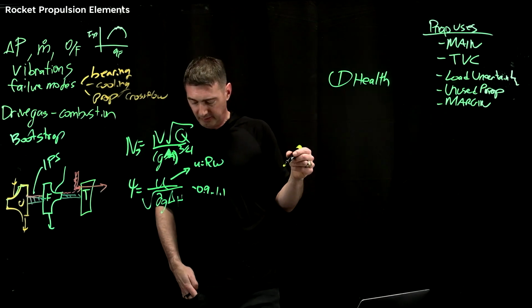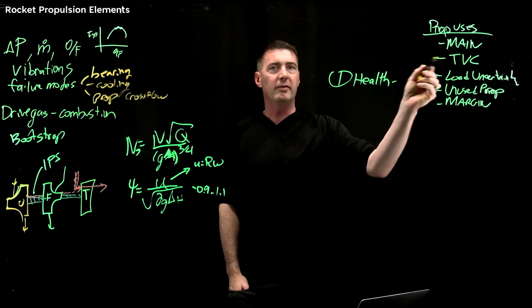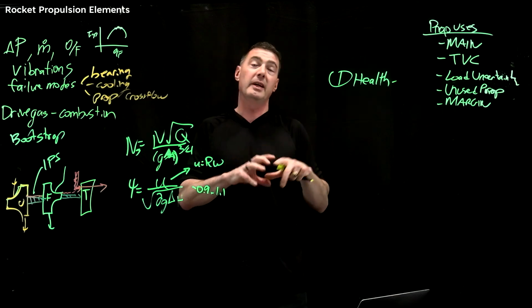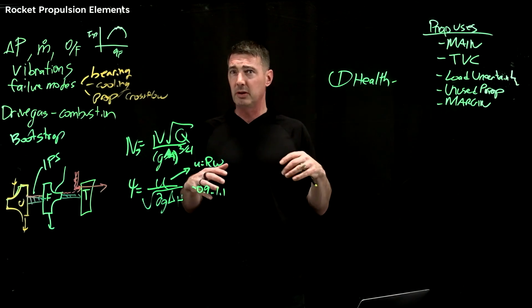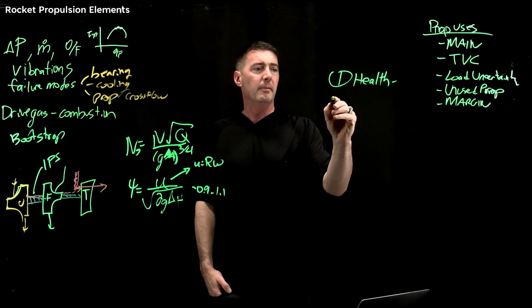So there are all of these things that you will want to do health check wise. If you have TVCs, you might do a wiggle of your TVCs, right? Do some valve clicks while you're dry with your rocket. So there are all of these things you're going to do before you step to the next configuration of the rocket all the way up.